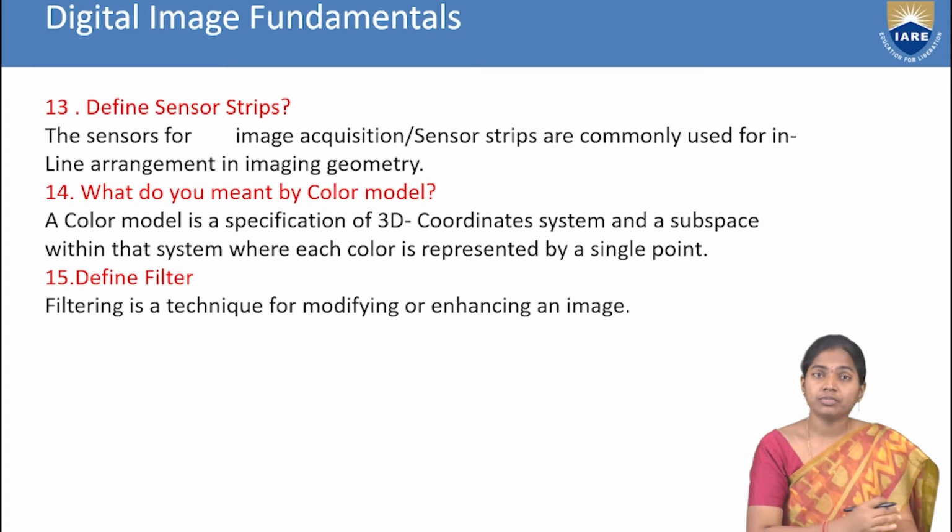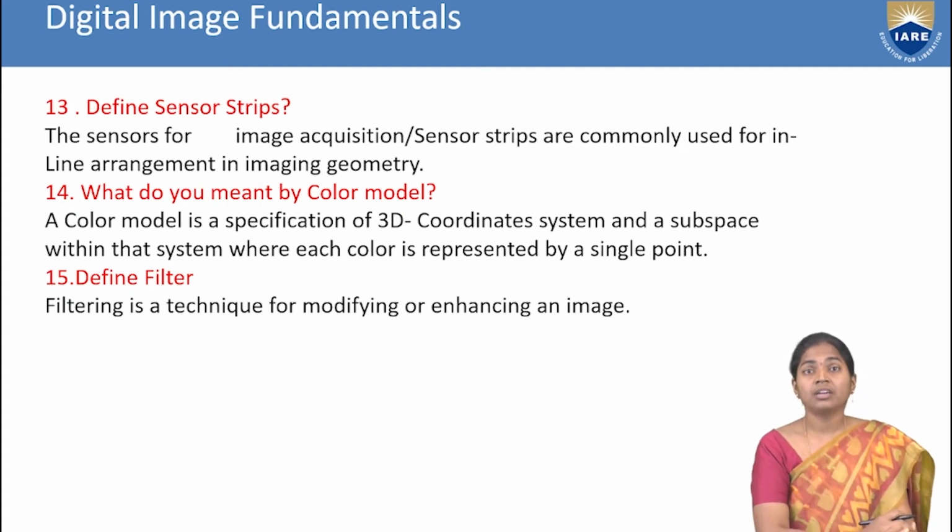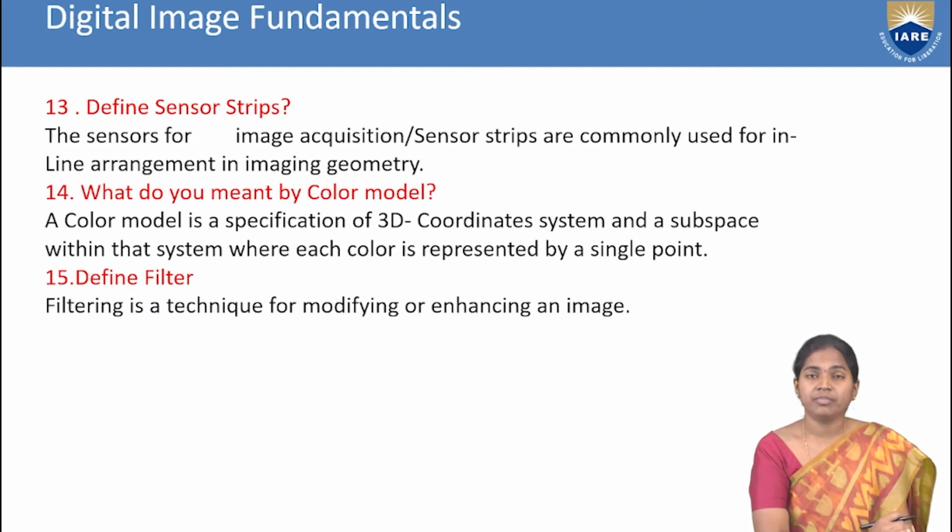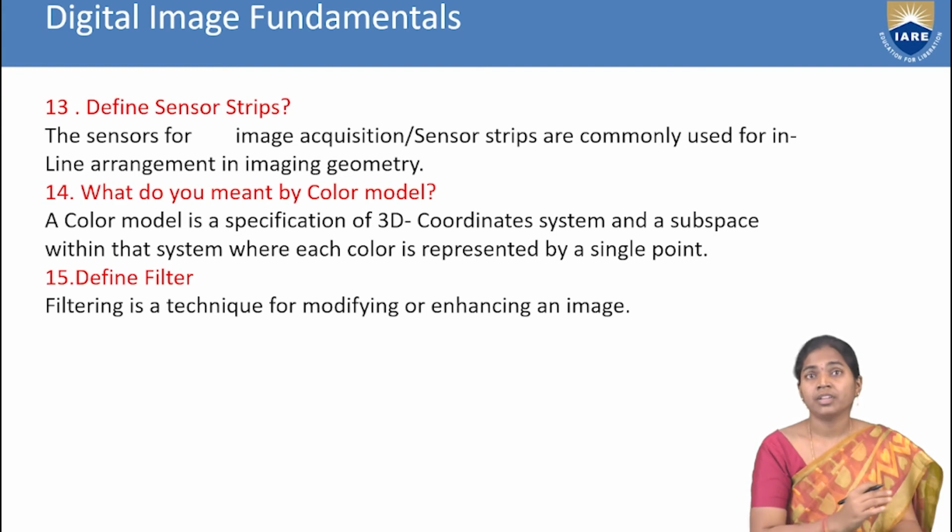In image processing, a low pass filter gives smoothening of an image, and a high pass filter gives sharpening of edges. These filters are basically used in image enhancement. In image enhancement we use median, average, maximum and minimum filters, which are all order statistic filters. With the median filter we can remove noise, in particular salt and pepper noise. With the maximum filter we find the brightest point in our image, and with the minimum filter we find the darkest point. The average filter and Gaussian filter give smoothening of an image.